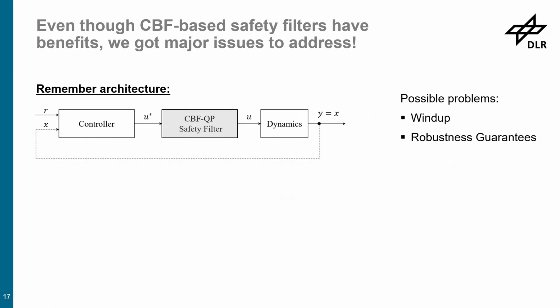And those things are normally done just for your LTI closed loop system, on a certain operating point. If you place a safety filter right behind it, it will adjust your input from the controller, right? And if it adjusts the input of the controller, it will shift the pole location of your closed loop system, right? And if the safety filter is not designed such that those poles are constrained to a certain region or analyzed with respect to that, you maybe become very unstable, right?